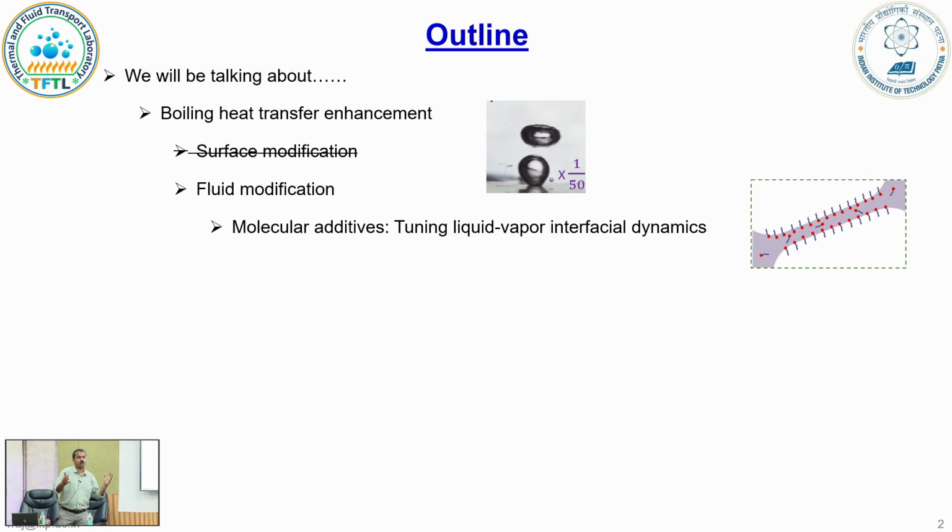So you can very well control the interfacial properties and behavior, and accordingly, without focusing or without relying on the surface, which is tricky to handle because there are issues of fabrication as well as fouling and degradation with time, can we do something by doing modifications at the fluid level? And this is not nanoparticles, so we are essentially primarily not modifying any significant properties of the fluid. These are molecular additives which dissolve and do not change other properties significantly.